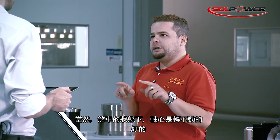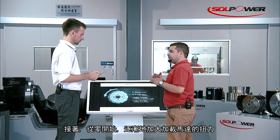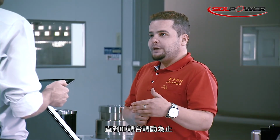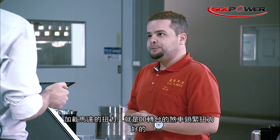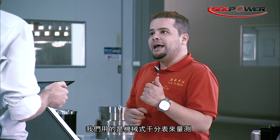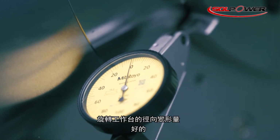In that situation, the shaft is locked. Then we gradually start applying torque until the DD rotary table turns. That moment gives us our clamping torque. Regarding the clamping rigidity, we use a dial gauge to measure the radial deformation of the rotary table.